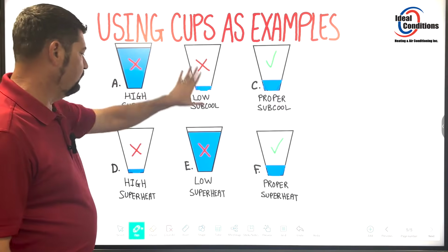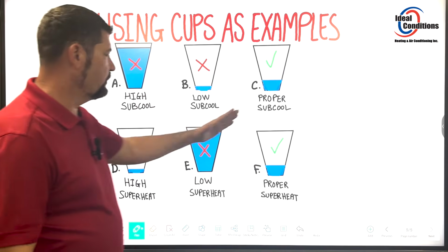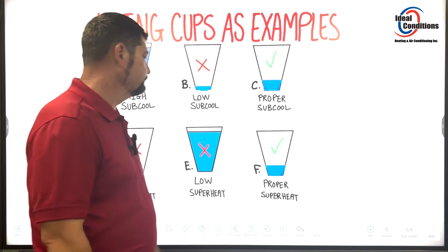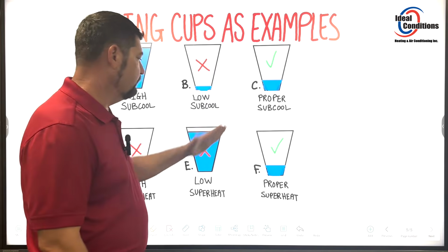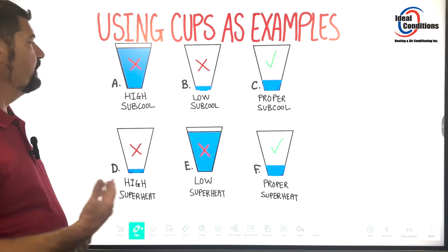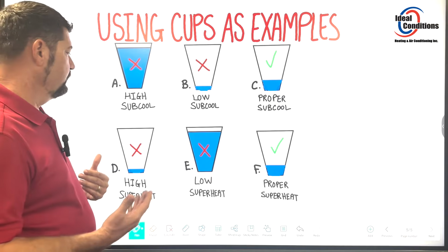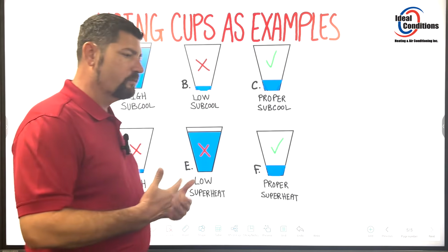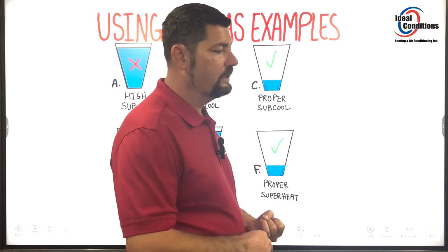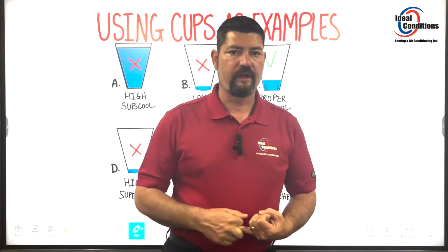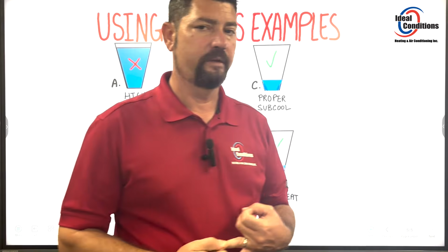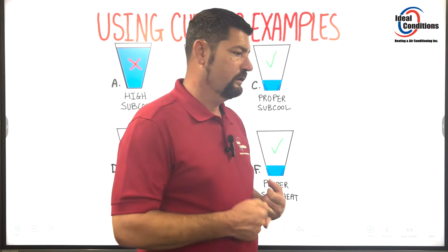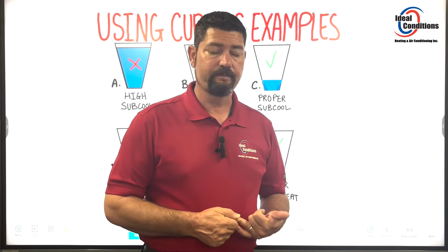I have the X's on what you don't want and the check marks on what is good. Okay, and so it's when we start to match these up is when we start to better understand where our mechanical problems are. Do I have a bad expansion valve? Do I have a pre-screen that's just clogged up, on that piston, right?